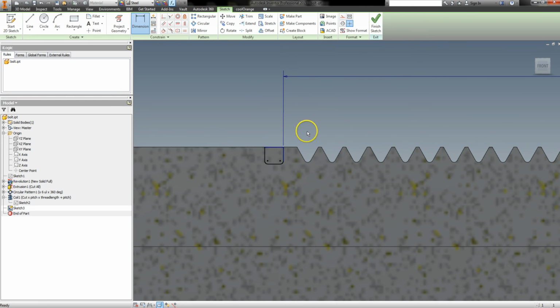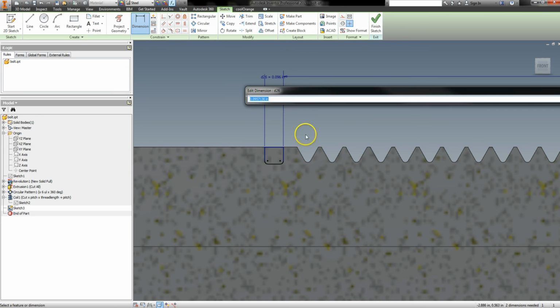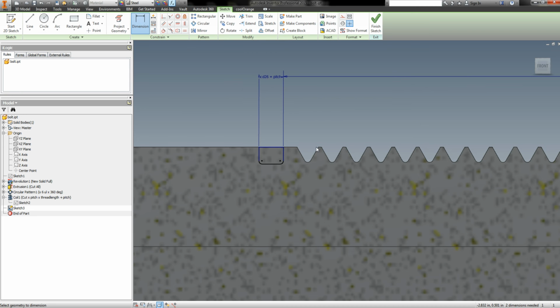Now I want to say you usually oversize your groove relative to this profile of the cut. So right now I know that this gap right here is 0.875 times the pitch, as determined when I sketched out my thread profile. So I'm going to let this one just be pitch. That'll mean that I have 0.125 times the pitch of clearance. And I think I'm quite comfortable with that.